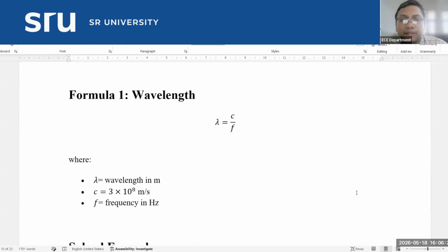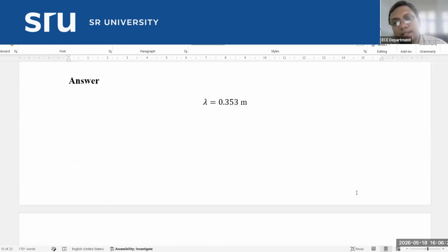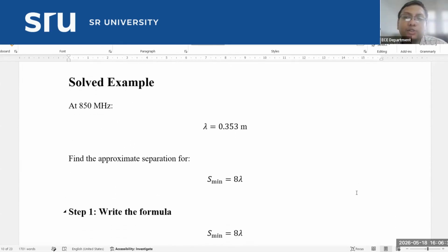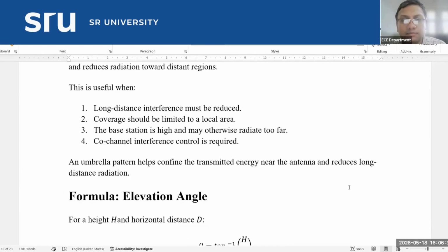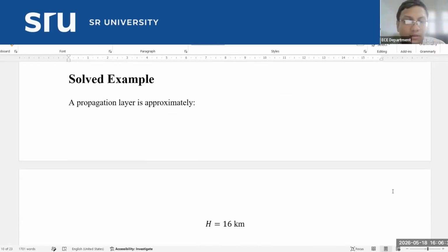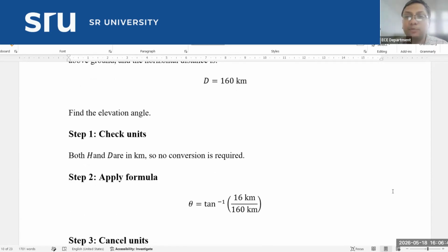So we need to keep in mind that a high gain antenna should preferably be used for transmitters, not for receivers. When the user is moving, this is also very important. Generally, for point to point, there is no problem. We can use a high gain transmitter and high gain receiver, and it will give benefit only.